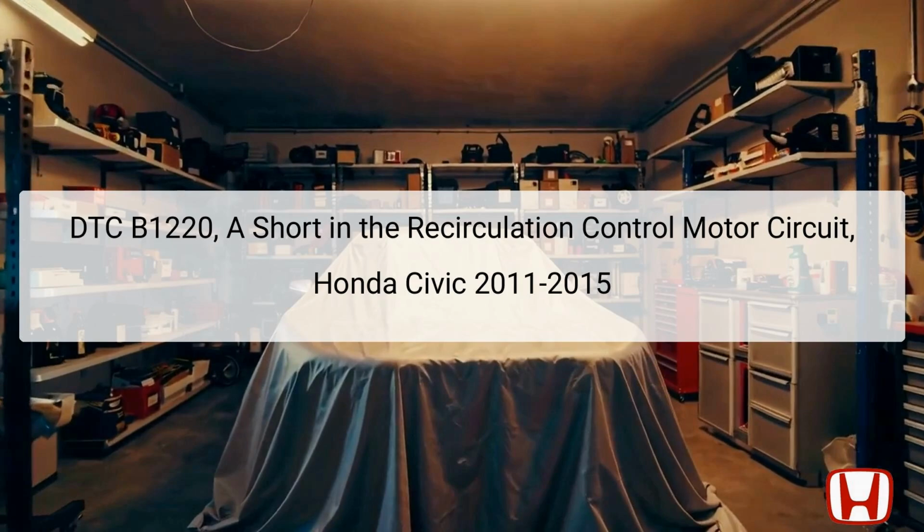The DTC B1220, also known as DTC Indicator 56, indicates a short circuit in the Recirculation Control Motor circuit. This trouble code is relevant for the Honda Civic models from 2011 to 2015 and signifies a malfunction that may affect the vehicle's climate control system.